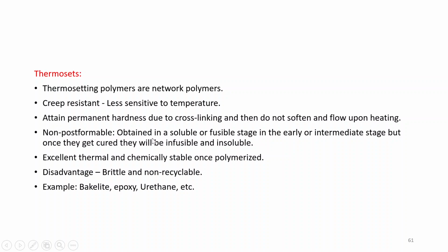flow upon heating. They are not post formable and are obtained in a soluble or fusible stage in the early or intermediate stage, but once they get cured, they will be infusible and insoluble. They are excellent thermal and chemically stable once polymerized, and the disadvantage is that they are brittle and non-recyclable.